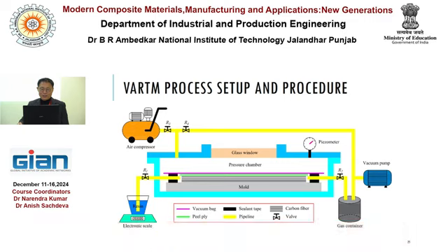An air compressor is needed, an electric scale is needed, a vacuum pump is needed, and a gas container is needed. These four pieces of equipment are around the manufacturing bed. Inside the bed there is a lower mold, and there are many fiber preforms here. The green one is the peel ply. This is one of the elements used for VARTM, and this is the vacuum bag.